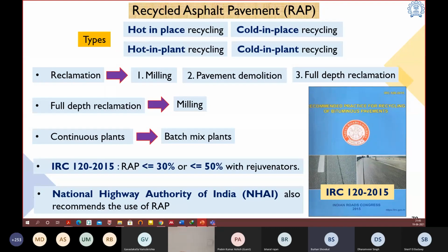pavement separately. As far as India is concerned, currently we had prominence of full depth reclamation for recovering the RAP material, but now we are undergoing a paradigm shift, wherein we are going from full depth reclamation to milling. This has advantages because it may enable us to stockpile the material in the proper form and therefore enables us a stringent control on the quality of the RAP mixes.